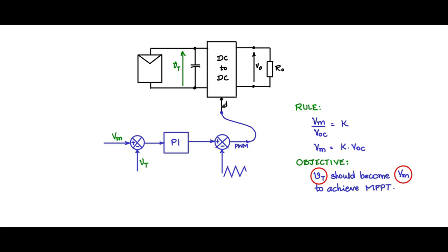Now this duty cycle will change by going from 0 to 1 or 1 to 0 depending upon which type of converter, and appropriately modulate the input resistance seen from the PV panel, which will appropriately position the load line and therefore change the value of Vt.